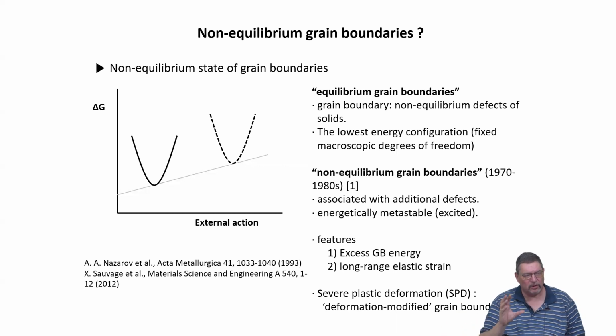So I'm talking here about conditional equilibrium again. So as long as the grain boundaries are there, the non-equilibrium state has the higher excess free enthalpy as compared to the grain boundary structure, which has the same overall misorientation of the grains, but the grain boundary structure itself would be relaxed. So this is the equilibrium structure to compare to.